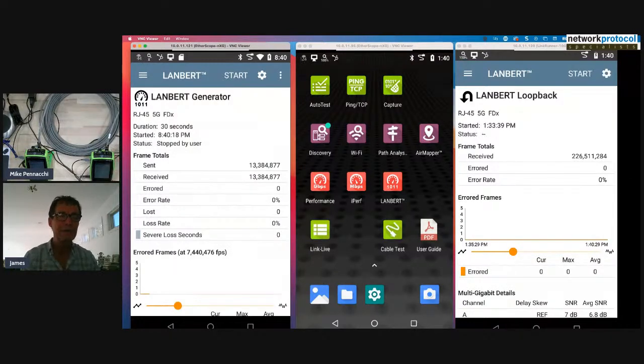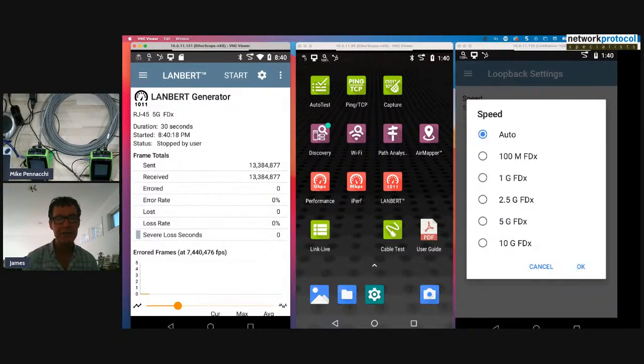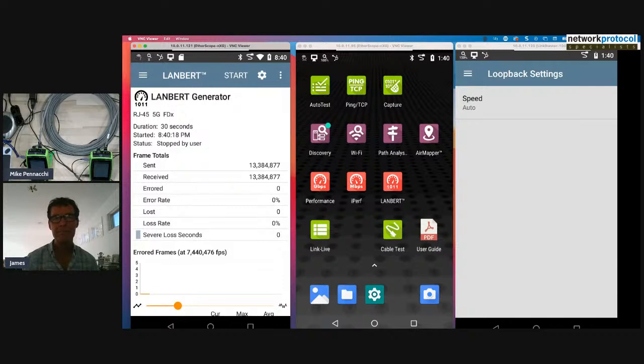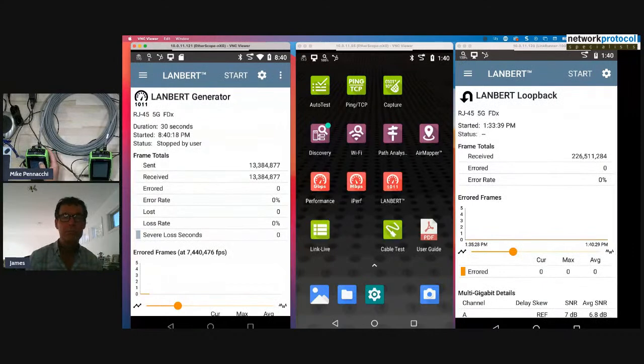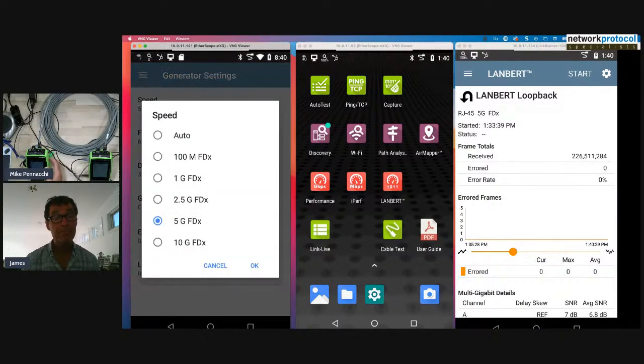Yeah. You know what I was going to say is, alien crosstalk typically is more pairs in a bundle than just one. So I don't think running 2 cables side by side would necessarily be enough. I think it's more of a bundling effect. Right. And also another place that we've seen a lot of alien crosstalk originate is in the patch panel. Yeah. In fact, more so than in the cable.